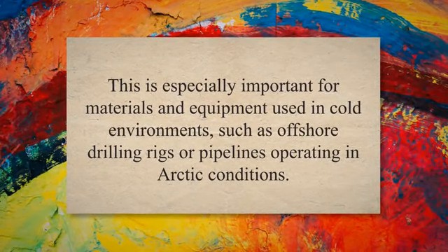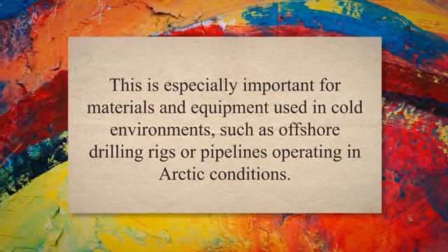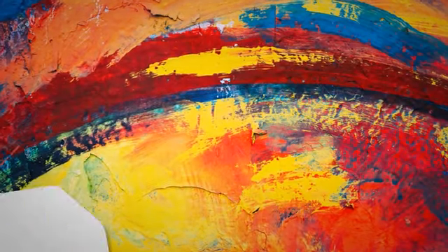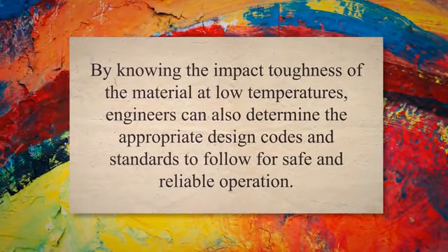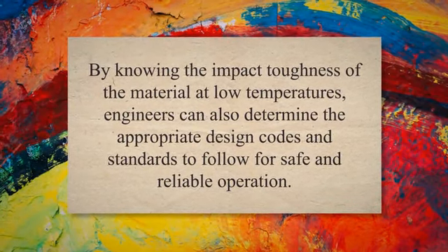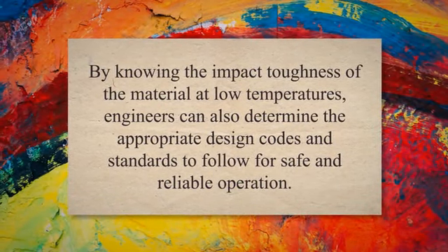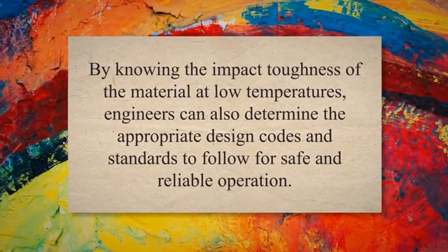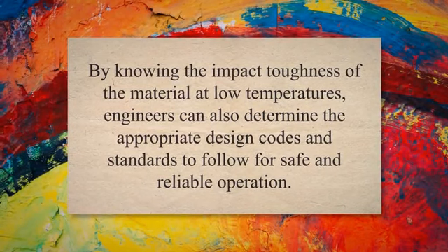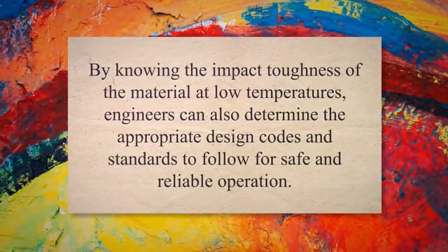This is especially important for materials and equipment used in cold environments, such as offshore drilling rigs or pipelines operating in Arctic conditions. The impact test results can provide valuable information about the behavior of the material or equipment at low temperatures and help engineers design structures that are resistant to sudden impacts or shocks in cold environments. By knowing the impact toughness of the material at low temperatures, engineers can also determine the appropriate design codes and standards to follow for safe and reliable operation.